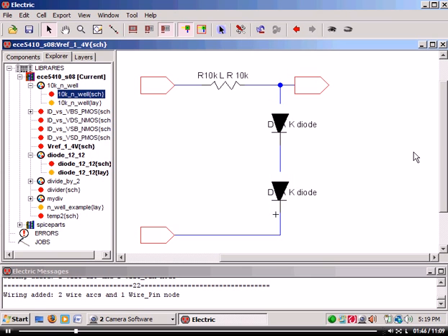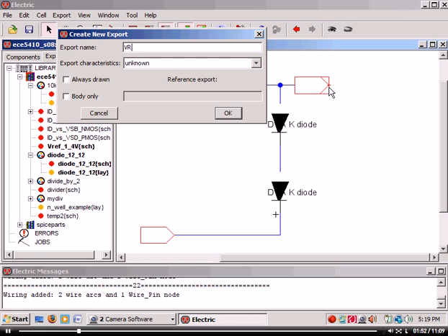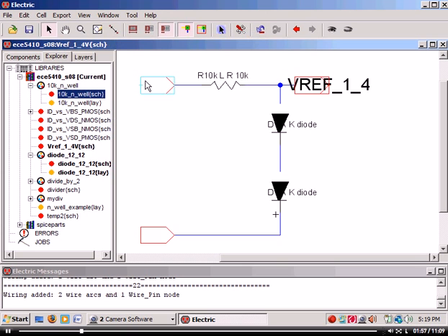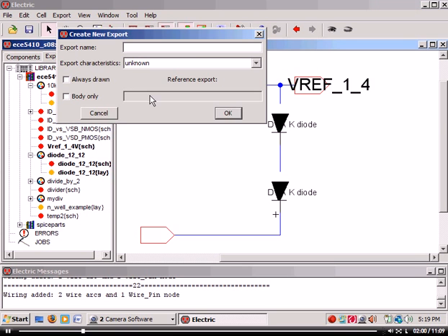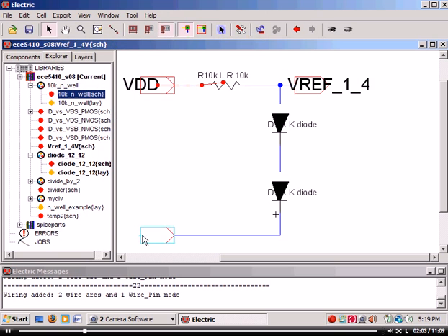Okay, so anyway, let's do Control E and call this vref 1_4. And why is that a reference voltage? Yeah, because it'll be 1.4 volts. So you designed your first reference there. Control E, GND. Let's do an LVS, and I should get at least 1, probably 2. I'll get this error, and then I'll get 1 over here, or maybe I won't, I don't remember. Thought I might.